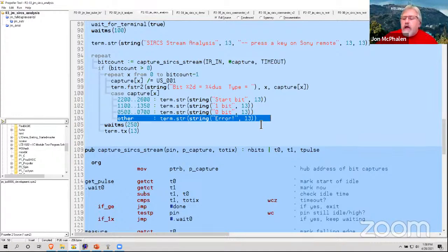So you'll have, for example, with this remote, which is a DVD remote and can control a TV as well, no matter what mode I'm in, when I press 1, I'm always going to get zeros in the command field, but the address field will be different. So a TV won't respond to the 1, but the DVD player will if it's in DVD mode.